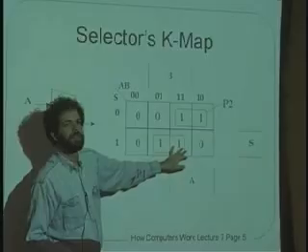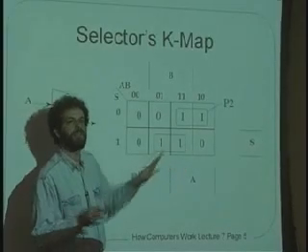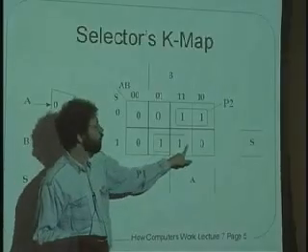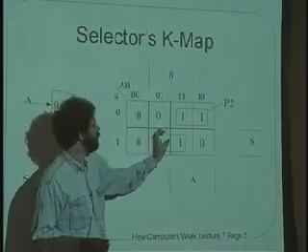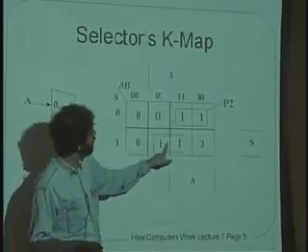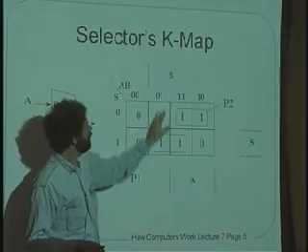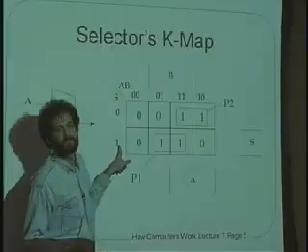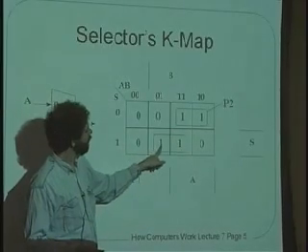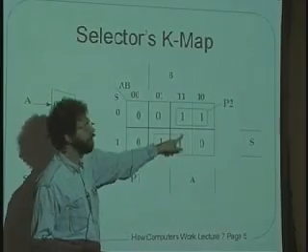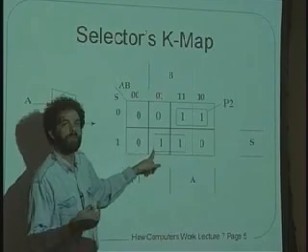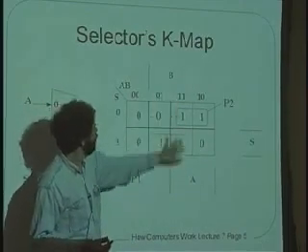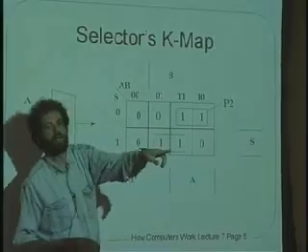But that group, 0, 1, 1, 0, doesn't stand for anything? No. Other than the individual ones, right. And then when we circle the two ones together, instead of separately. If I were to just circle this one over here, this would be B and A bar and S. That would be one way. But instead of doing that, I want a more simplified product term that has fewer inputs. And I circle both of them, and I get B and S, which is that lower AND gate there.